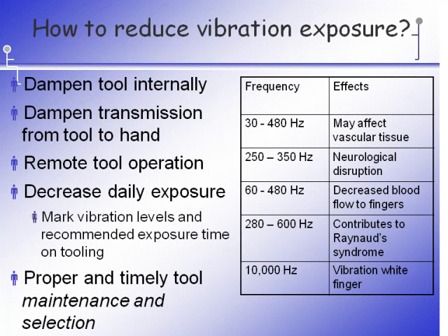If you have air hoses that are leaking and you're not getting the right PSI at the tool, it's not operating at the correct revolutions per minute. Therefore, it's operating slower. It might be less efficient. The vibration levels can go up significantly. Or if the tool is running slower, people might have to use it for a longer period of time. If the right abrasive material or the right cutting tool isn't available and they're using duller sanding paper that's already worn out, or a cutting edge that isn't sharp, then of course workers are going to be working much longer.